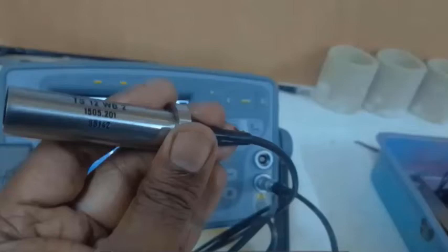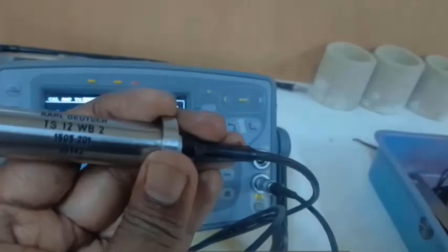Okay, so for this purpose we are going to use this cylindrical block which is made of the same material. The previous calibration that we just saw was done using a particular material. In order to use the same calibration, the sample material and the standard block used for calibrating the instrument must be the same, right?